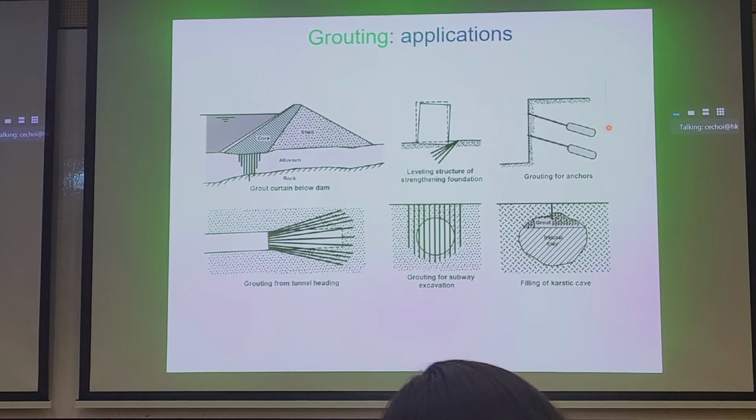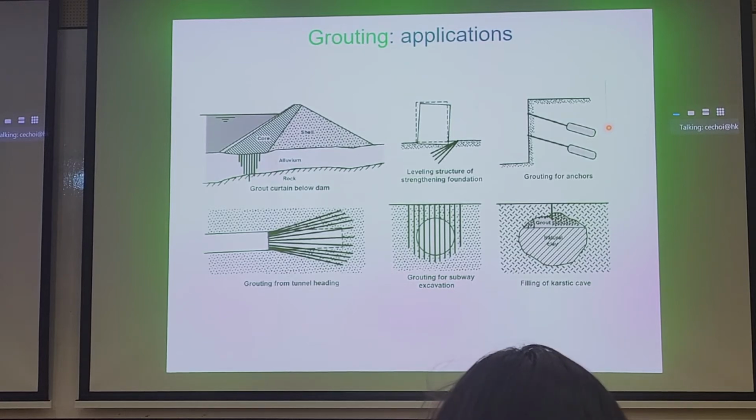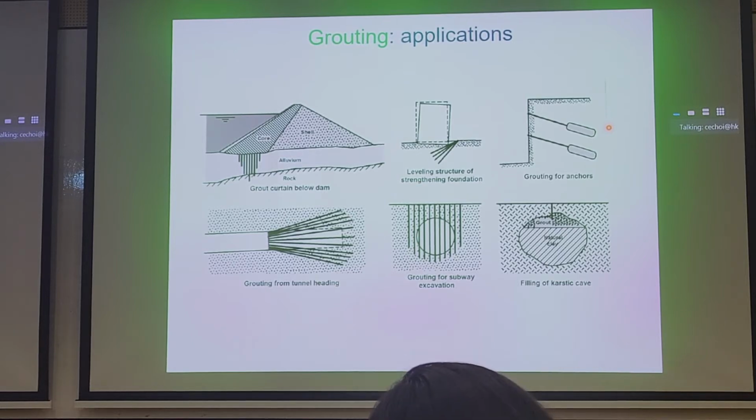Those ones we have to monitor once a year and make sure the pre-stress levels are correct. So that's why you see maintenance workers there once a year to make sure that the pre-stresses on each ground anchor is sufficient. Those are examples of ground anchors, and ground anchors are grouted at the tip to provide additional pull-up resistance in the ground.